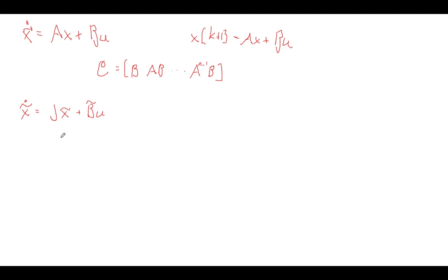And we've already seen how that really reveals the underlying dynamical structure of the system better than any other form that we have. And it turns out that controllability and observability is also very straightforward if you convert your system into this Jordan form. It ends up being a very clean way to think about controllability and observability. So to start, let's just look at a simple 2x2 system where I've done this equivalence transformation and I'm in Jordan form. I'm going to keep working in continuous time, but the results are exactly the same in discrete time.